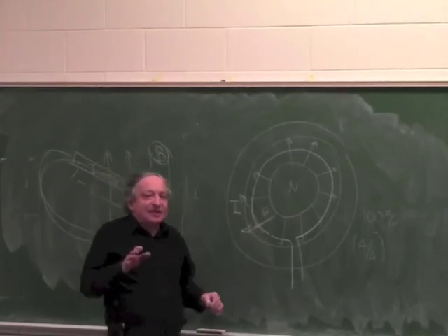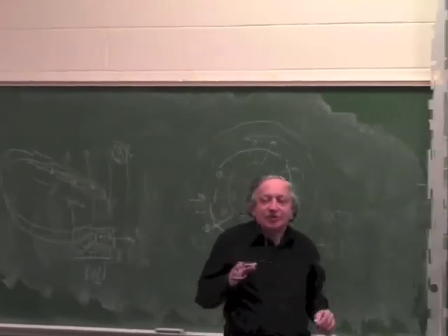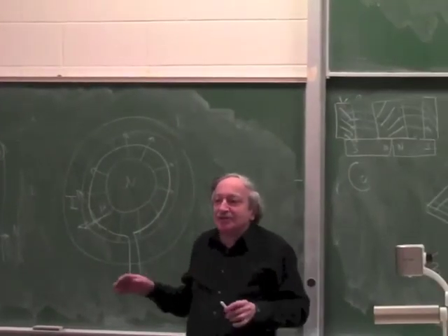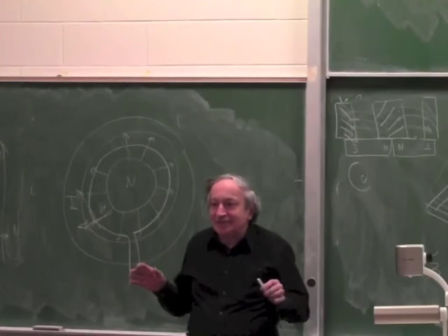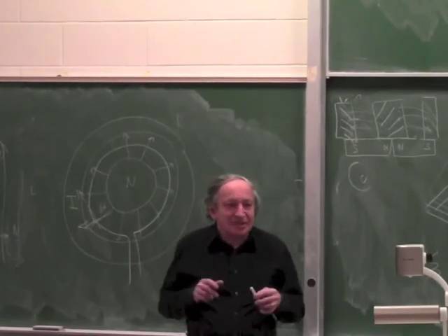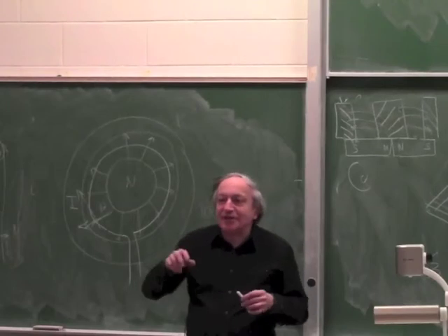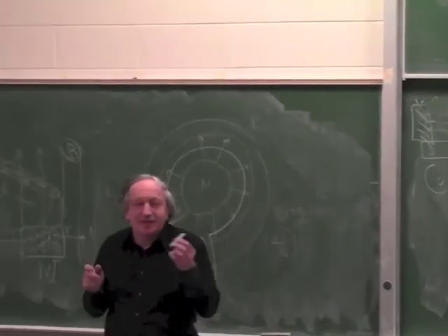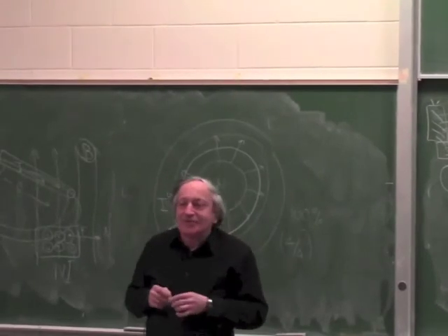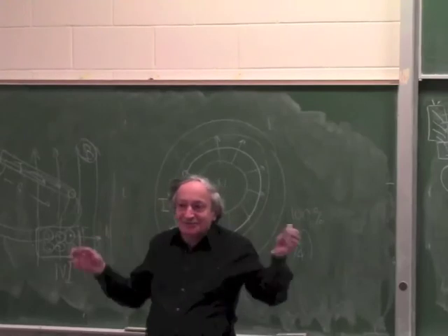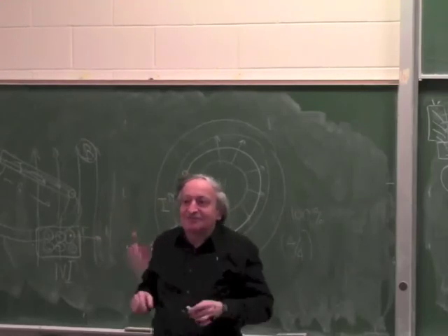Now the reason, by the way, why people want rotary not linear, is that in any mechanism, if you can make it rotary instead of linear, you are ahead. Because a rotary motion is much easier to build, much easier to seal. Right? You just have a ball bearing and you achieved rotary motion. Linear motion is much more problematic because you have slides and so on. You know, think of the human body. All the joints are rotary. Okay, because it's easier to seal.